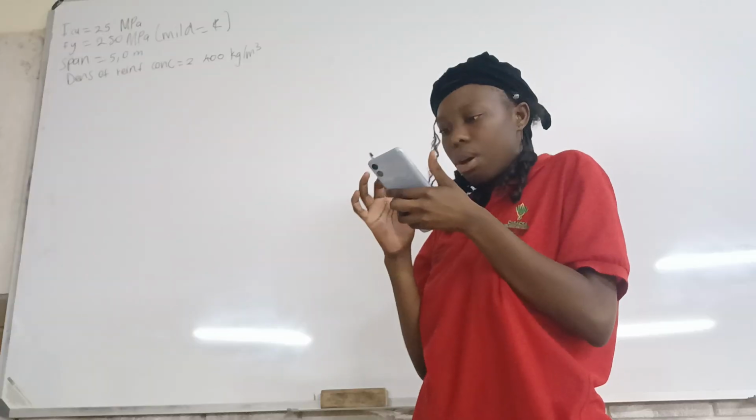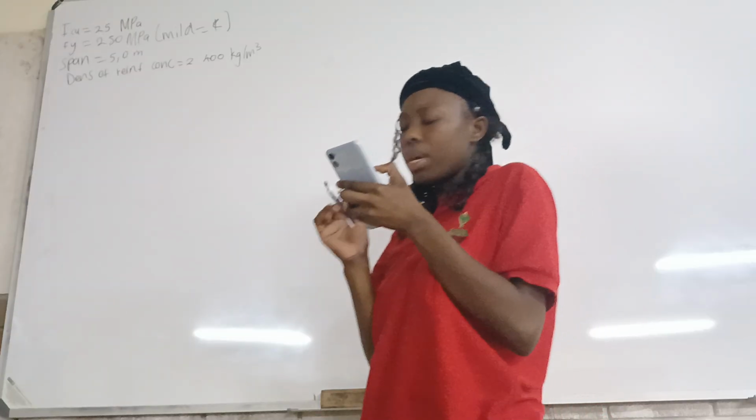So, what do we have? We have the beam again. Here is our beam, with the width of the beam. From here to there, it is the overall depth. And then here we have our bars. From the middle of the bars until where the beam starts, we have the effective depth. And then here we have the cover, which starts in the middle of this tension reinforcement bar. And then we have the width. They gave us a width of 220.